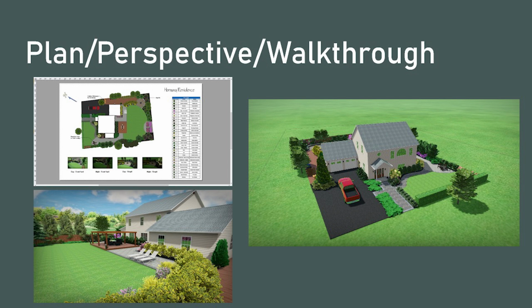We then had to input our own layers similar to AutoCAD, but in the Realtime Landscape software, you can lock and turn on and off a certain layer at any time. Being able to turn off specific layers is huge when creating large areas with large quantities of plant material, as things can get a little crowded. After scaling the background image, we set it in the correct area and locked it so it could no longer move or interfere with our future designs.